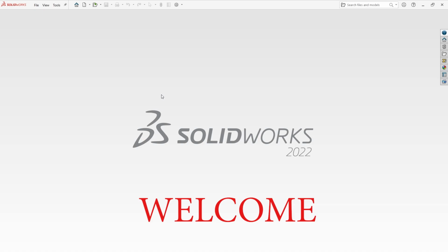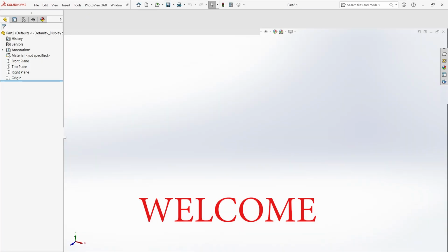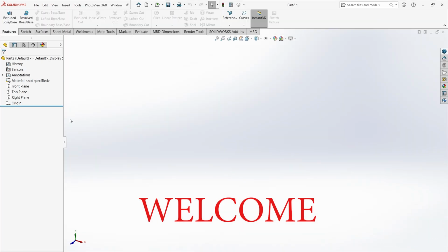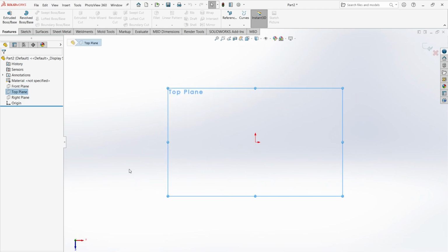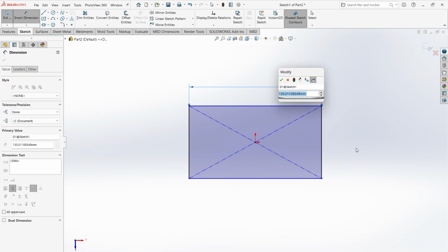Hello YouTube, this is a video on SolidWorks Static Simulation. So let's start. First take a new part, sketch, change the unit to millimeter, go on top plane, click on sketch, choose center rectangle, then give dimension.